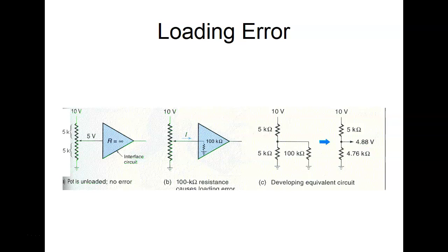So this is why these analog inputs on these program controllers and these devices have extremely high input resistance. But you've got to remember, as soon as you put your meter across that, you're adding something in parallel. And this would be a reason why your calculated values and your measured values might not be exactly the same. And we call it the loading effect.